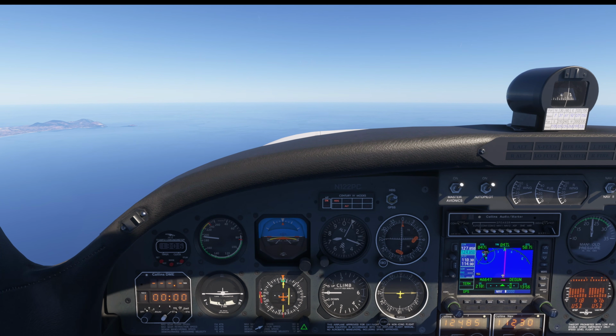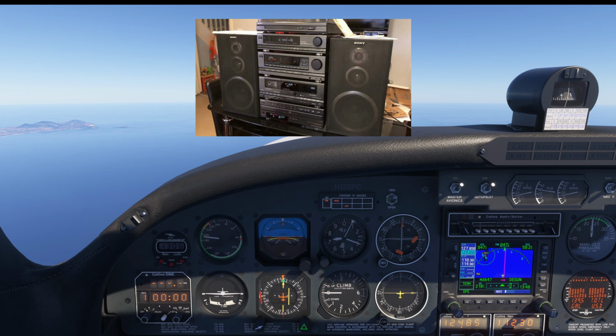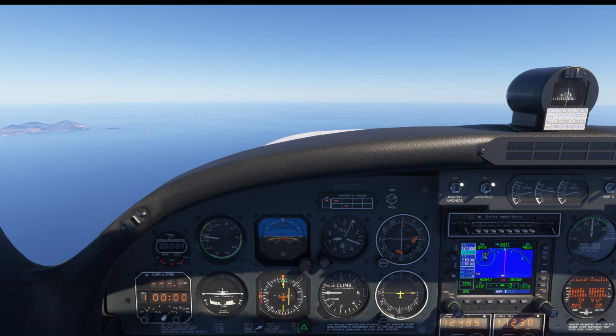Older autopilots do not have any place where you can plug that steering commands from the GPS. Imagine an old stereo unit without aux input. It may still sound great, but it won't play music from your smartphone. GPSS is an aftermarket option that solves this problem by converting GPS steering commands to fake heading bug signal.